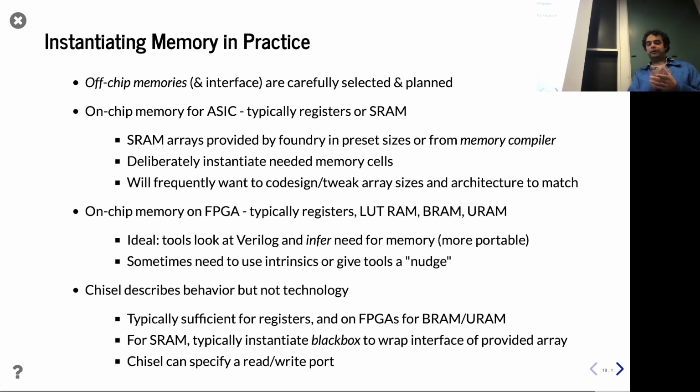And of course, we talked about in Chisel, we're going to talk about doing read ports, write ports, or even read-write ports. You can do all that. I would say the most common mistake people have when they try to get BRAMs out of a Chisel memory, it doesn't happen. First of all, it needs to be a sync read memory, not just a mem. But limit the number of ports, right? If you have like 4 ports, it's not going to work. You only have up to 2 ports, right? So that's the limit for BRAMs in the hardware.